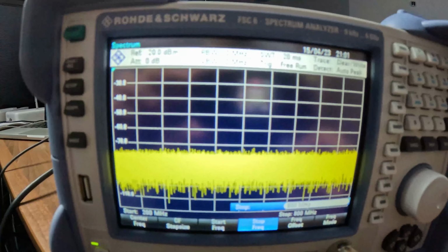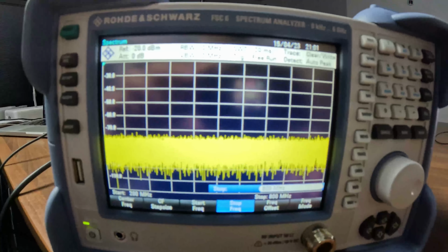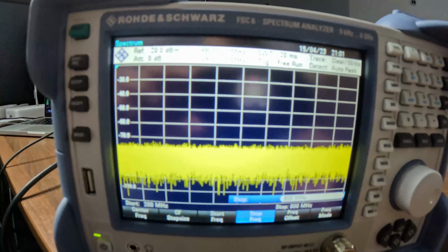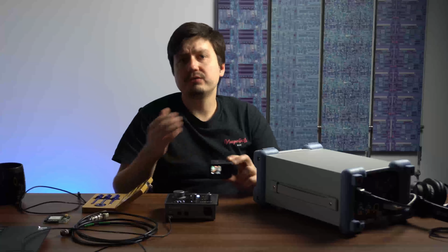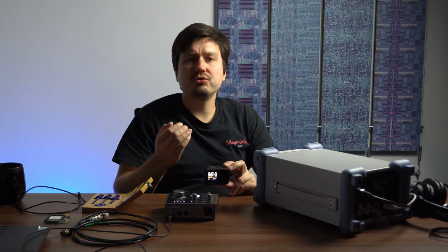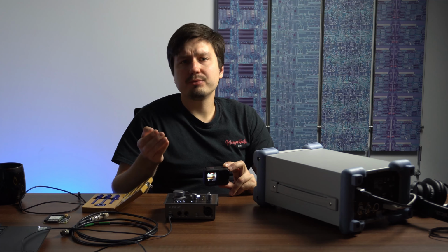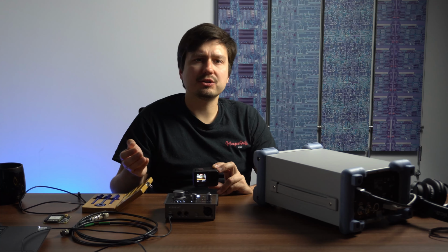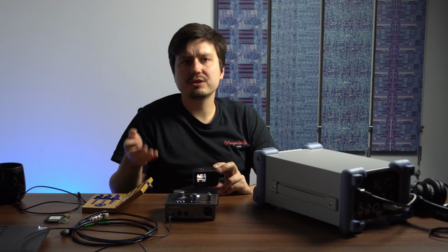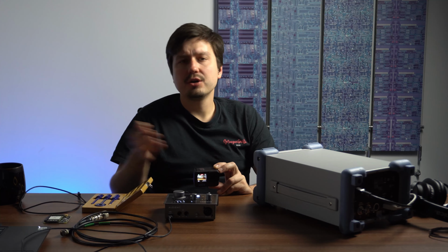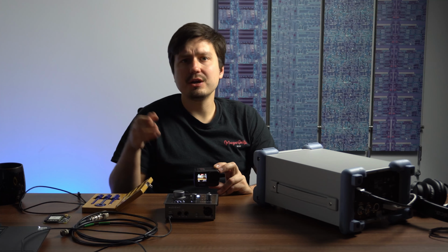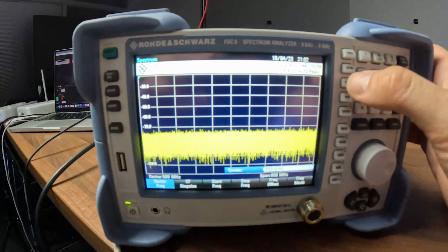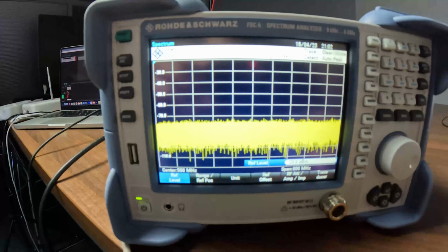When we narrow it down to a specific section, we can see a lot more. Now obviously, as I said before, it really matters what you are doing and what sort of problem you've got. If you already know that you're failing at a specific frequency, then you're obviously going to set the frequency range with a center frequency at the frequency that you're failing at. So the next window that you really need to look at is the amplitude window.